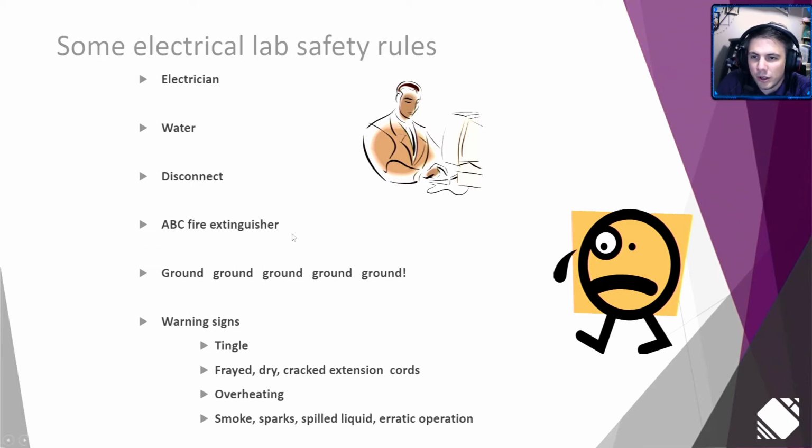The fire extinguisher, you'll see fire extinguishers in every electrical room. It's required by code, and typically we put one in by each door, so that regardless of where an electrician is working in the room, if a fire happens, they're close to a fire extinguisher. But you can't use a standard water fire extinguisher on an electrical fire, because it's just going to make the problem worse. So you need one that's rated for electrical fires, which ABC fire extinguisher is. ABC is the different ratings of fire extinguisher.